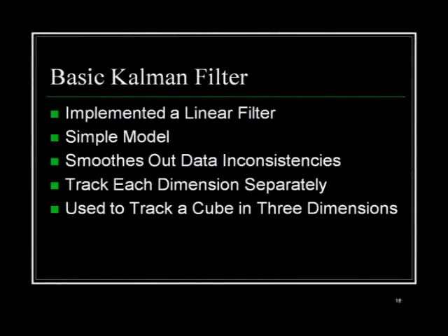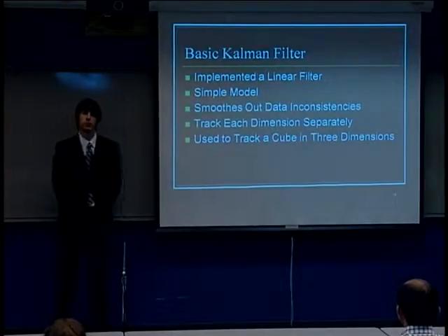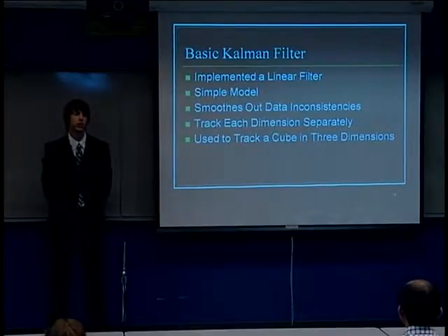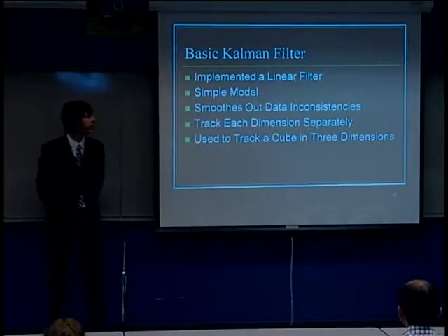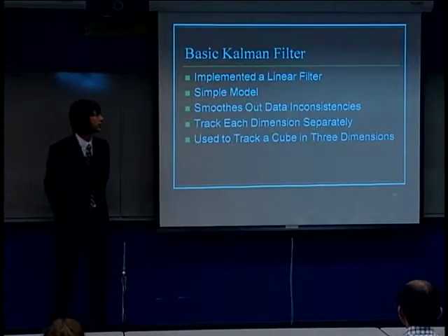All right. Well, my part of the project had two parts. The first was actually filtering the data. I used a basic Kalman filter at first. This was just to get a baseline of what we were going to do to begin with. So the basic Kalman filter is a simple linear filter, and I used this for a couple of reasons. It was easy to implement.